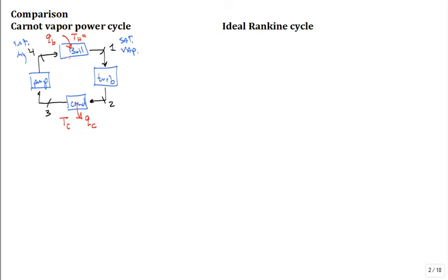What was the equation for solving for, let's say, the work out of the turbine? Well, we're going to get the work out of the turbine in terms of the change in enthalpy. Comes in high enthalpy, goes out low enthalpy. How about the heat that's rejected in the condenser? It's in terms of enthalpy. The heat transfer out of the working fluid in the condenser per unit mass of the working fluid flowing through the condenser is a change in enthalpy. Comes in relatively high, goes out lower.